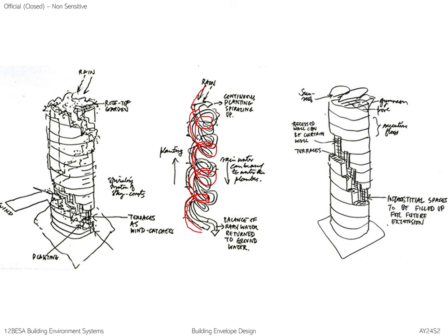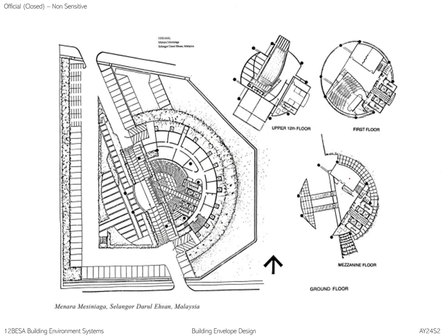So okay, terraces and then the recessed wall can be curtain wall. In this case, you have the best of both worlds. Around this building is very nice greenery, right? So you want curtain wall, but at the same time, you want to be conscious. You don't want so much solar glare, and you don't want so much solar heat gain into the space. So how does he deal with it?